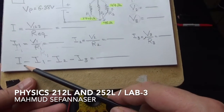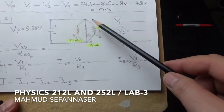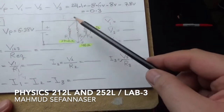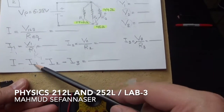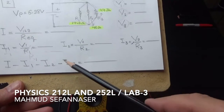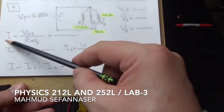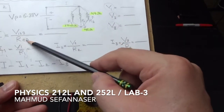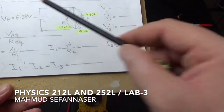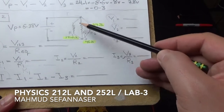So to make sure this circuit is correct and Kirchhoff's first law works very well, we need to go through this equation. So we need to subtract I1, I2, I3 from I here. And I, guys, can be calculated from V123 divided by R equivalent. So what is V123 here? The V123 here is the voltage across these 2 points here.